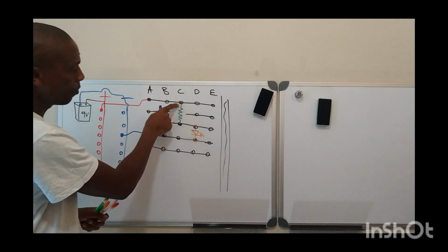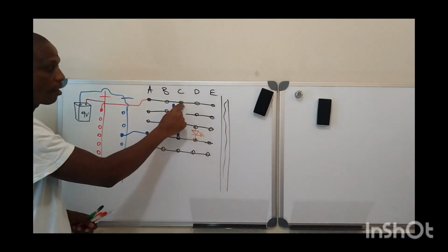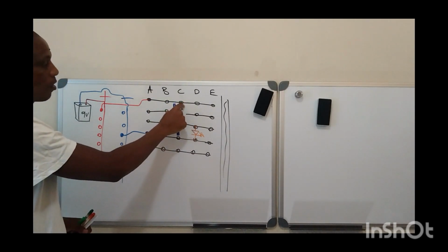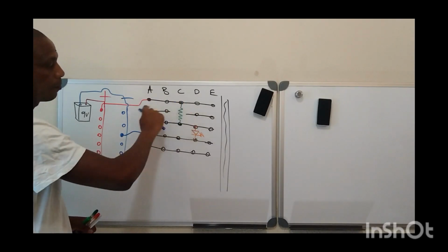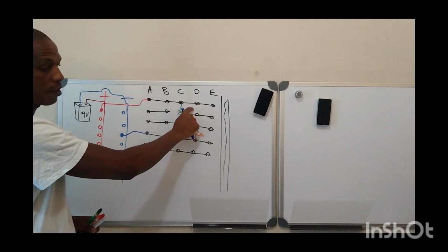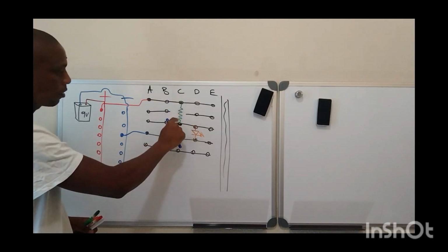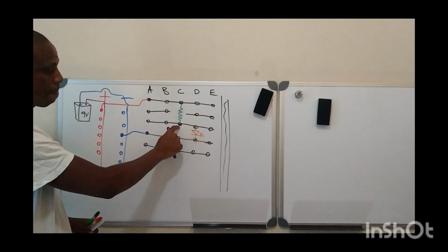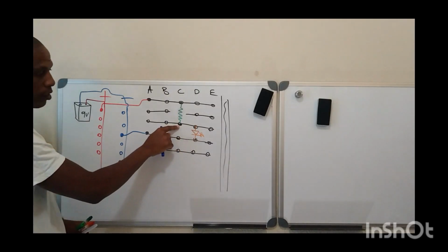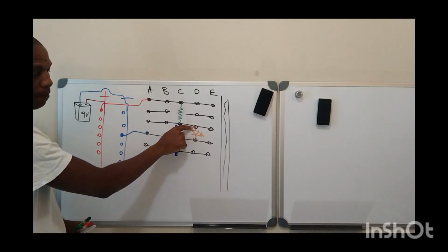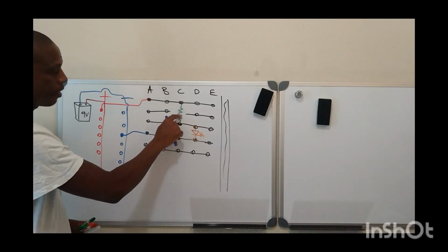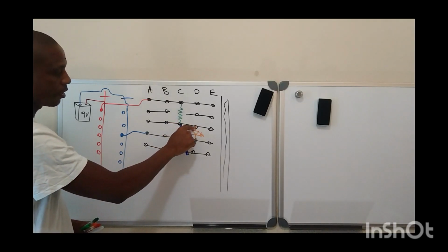Then here we connect the first end of the resistor to C, which is the positive 5 volts, okay? Yes, sir. Then the current will run through the resistor to this end. In line with the end of the resistor, you must connect an LED, okay? Yes, sir. Then the current will come out this side and run in this direction.